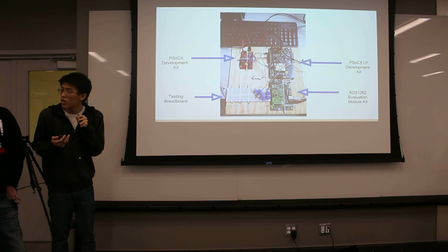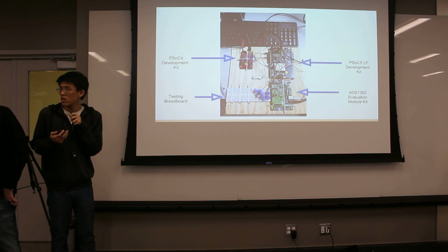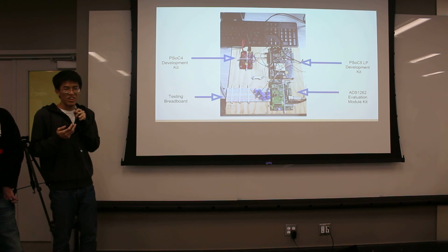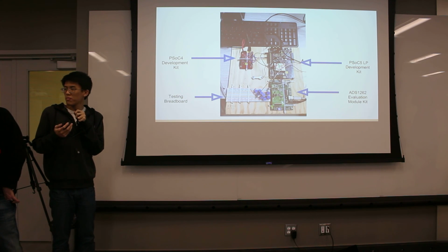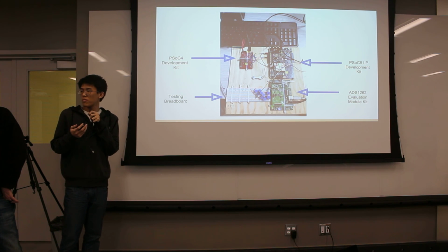You're using the instrumentation amplifier of the PSOC 5? We made one. In PSOC 5? Yes. Can you talk about that? It's good? Yes. Not good. Could be better. That one is not so low noise that you probably do want to go to an external, specifically designed instrumentation amplifier and then go into the PGAs of the ADC as soon as possible. So that instrumentation amplifier should be right at the load cell.